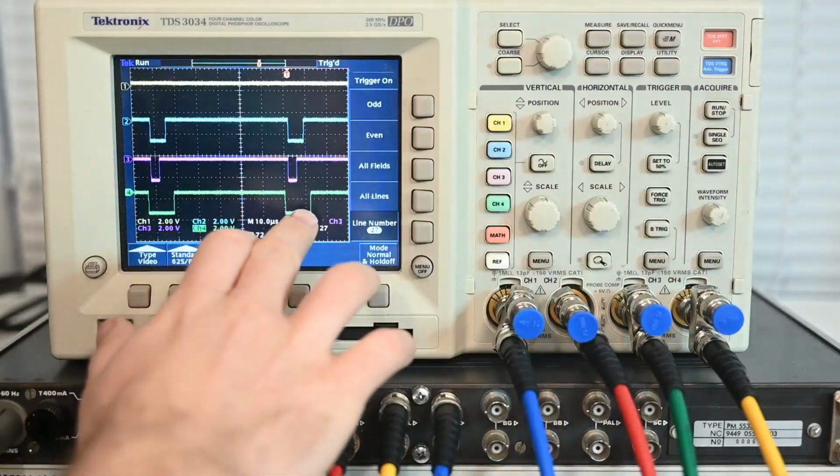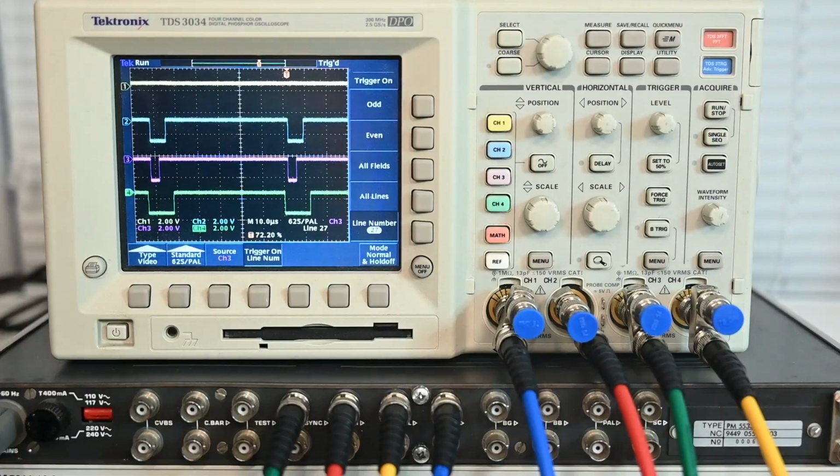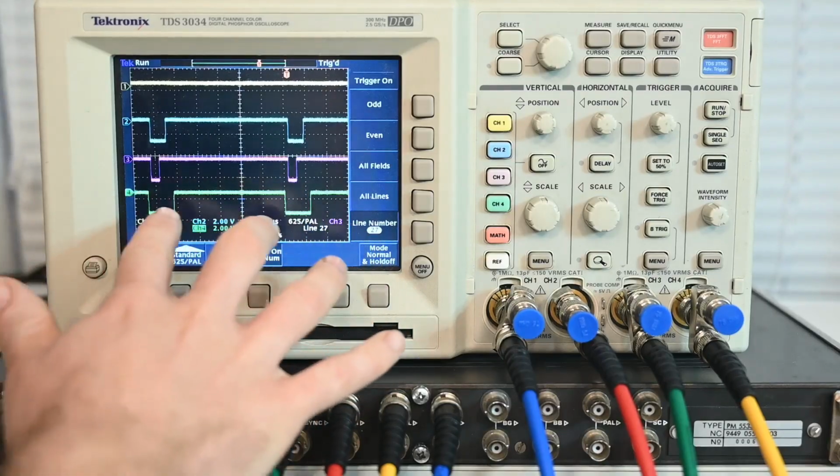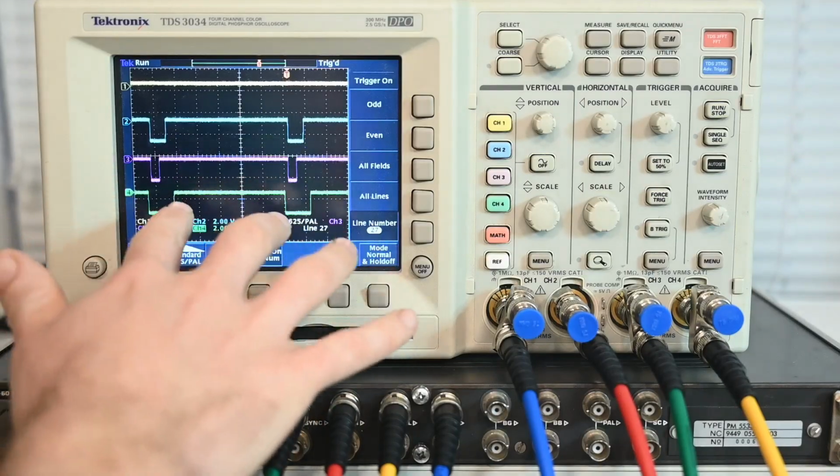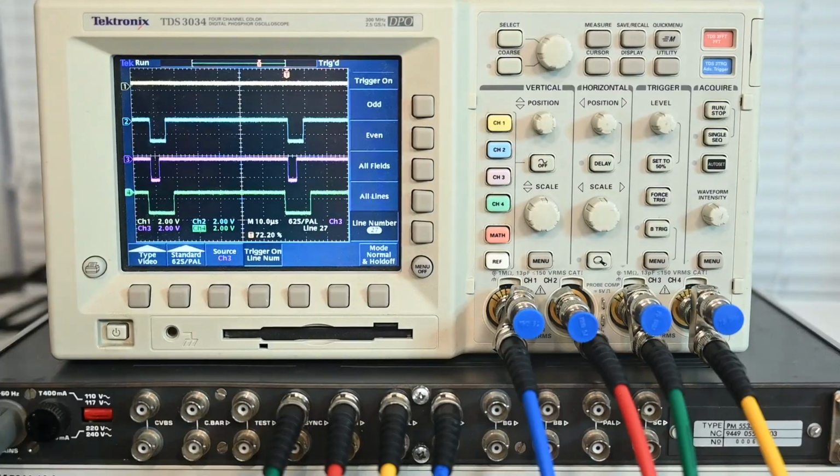Now when this signal is high, this is indicating to any piece of video equipment that this is a time to be inserting your signal into the final output signal. So if we think about a monochrome camera or even a color camera, the tubes are always going to be outputting something, but we don't necessarily want that output in our actual signal. So this is really just saying to the camera, by the way, this is the time to gate your output into the signal that you're generating. So anyway, that's the monochrome 4, and next we will move on to color.